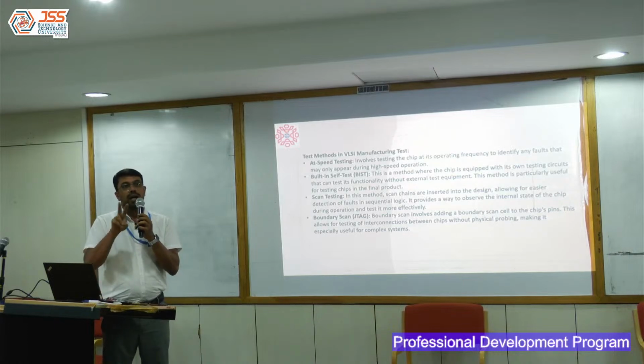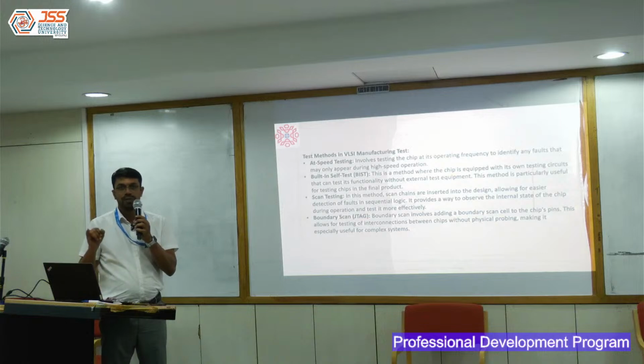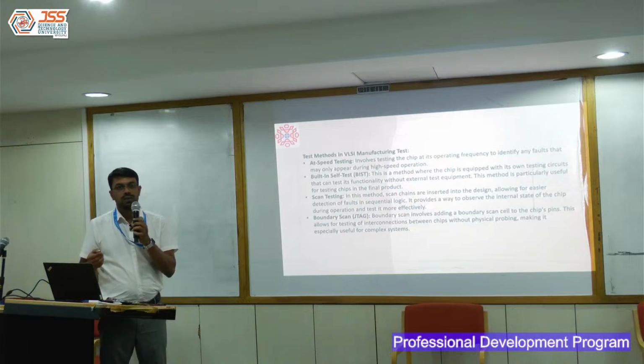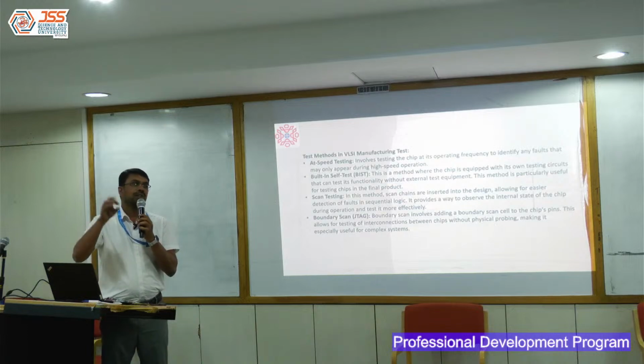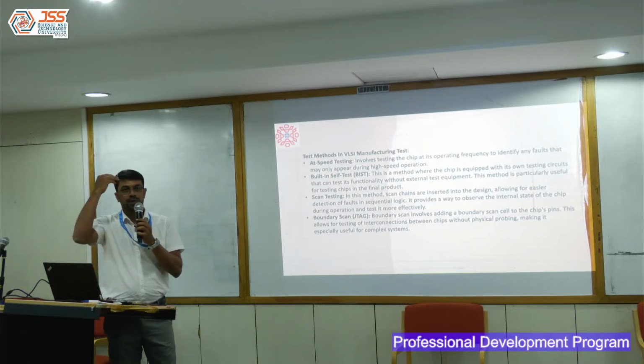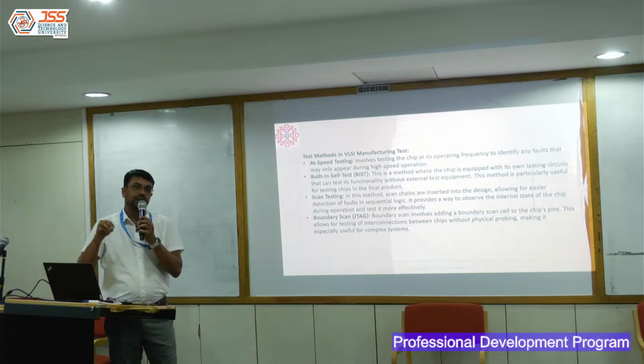So these are all IPs. So when you design a chip, all this matters. What's your functional frequency? If my functional frequency is above 1 gigahertz, then I'm forced to go for an on-chip PLL. If I go for an on-chip PLL, I'm forced to use an on-chip clock controller. That clock controller is nothing but, you can imagine it to be a huge mux which selects between your test clock. Test clock is nothing but my scan clock, or the clock which I use for testing for this manufacturing defect.